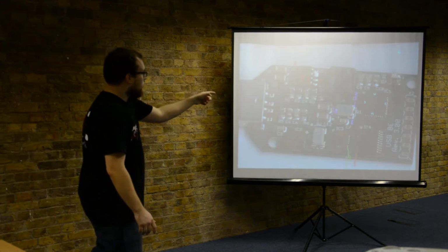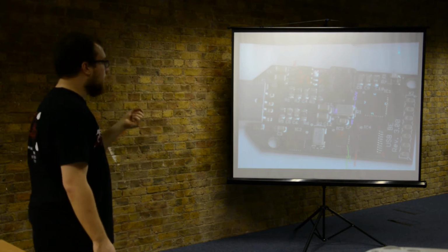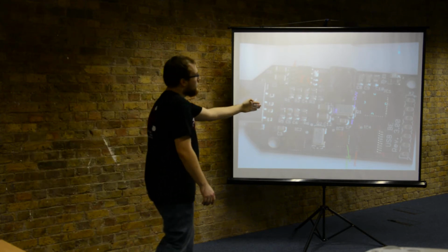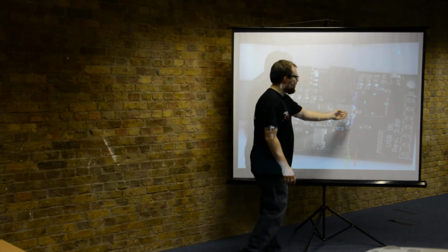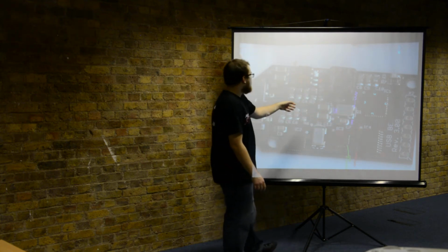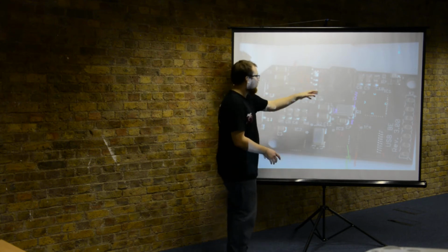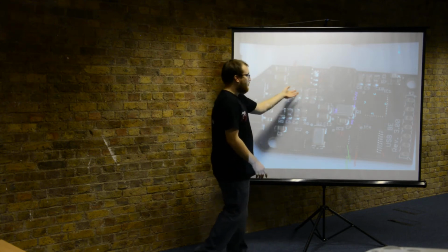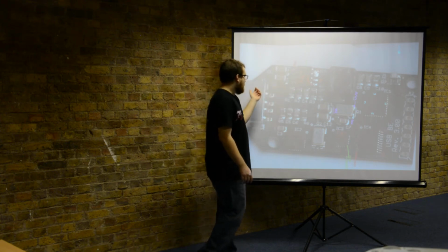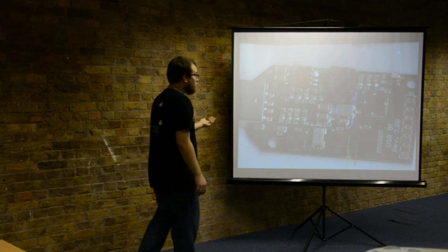The chip you see on the far right is the actual ASIC miner chip itself. And over here you can see the crystal that is driving that chip. There's some interface logic around here. And another important part in these sort of little systems is the voltage regulation, the buck boost regulator part. This is a buck regulator that goes from 5 volts to 1 point something volts.